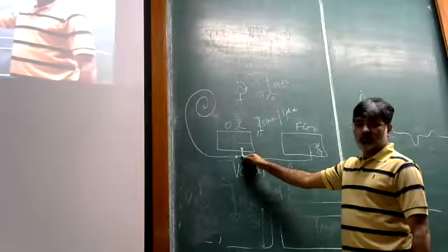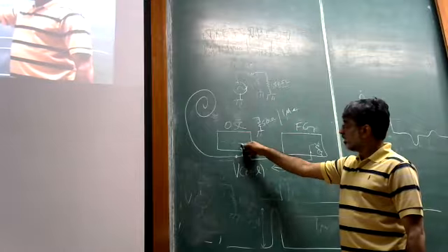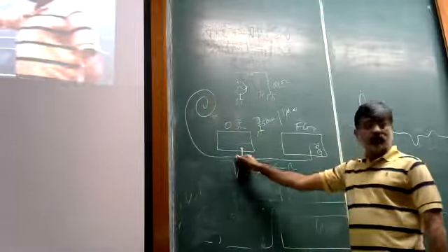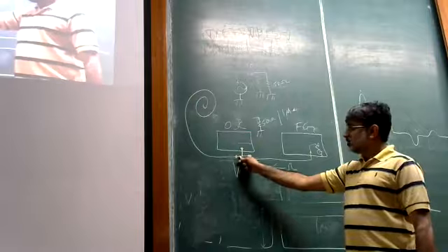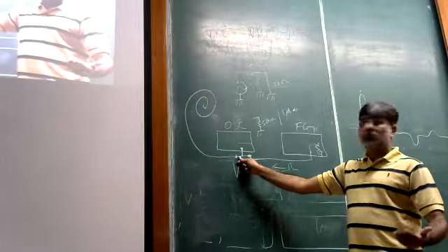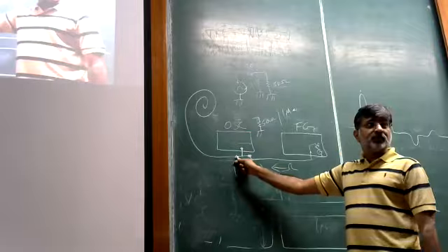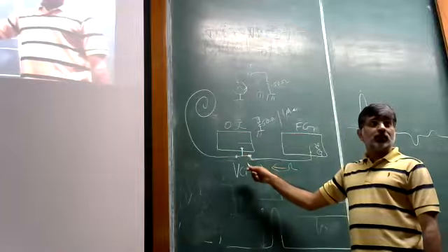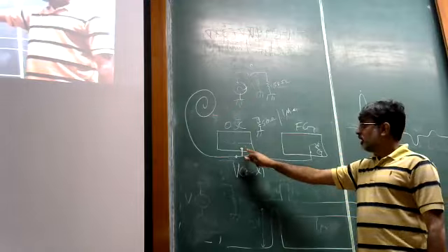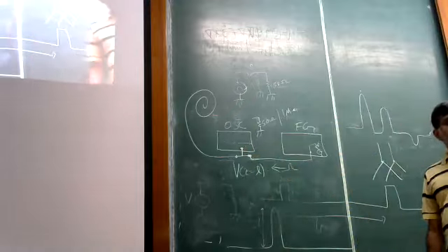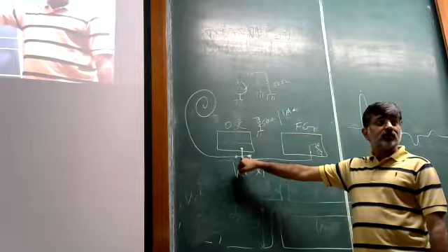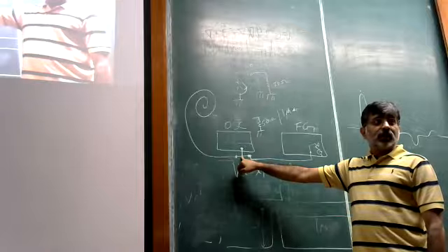We saw 2/3 on the oscilloscope. It traveled a long distance and came back. What he's saying is that at this point, again, there is a problem, in the sense that there's an impedance matching problem, because this is a 50 ohm line, but it's seeing a 25 ohm load: 50 ohms because of the oscilloscope, and 50 ohms because of this line connected to the function generator. Which means that at this point, there's actually going to be another reflection and transmission.